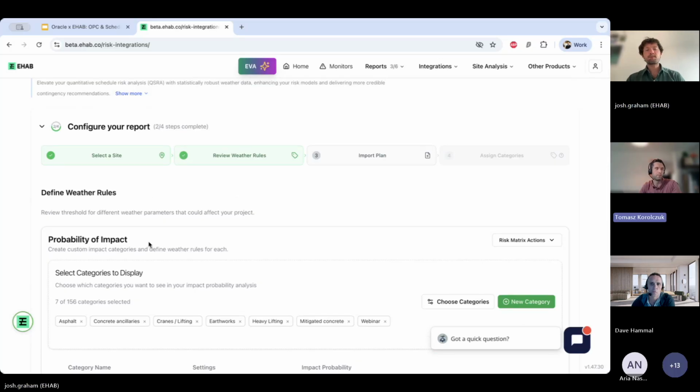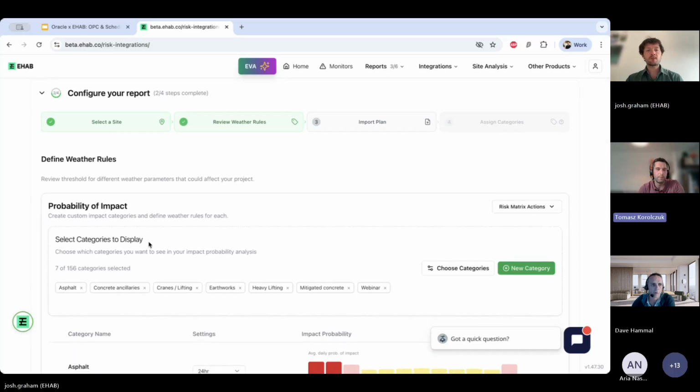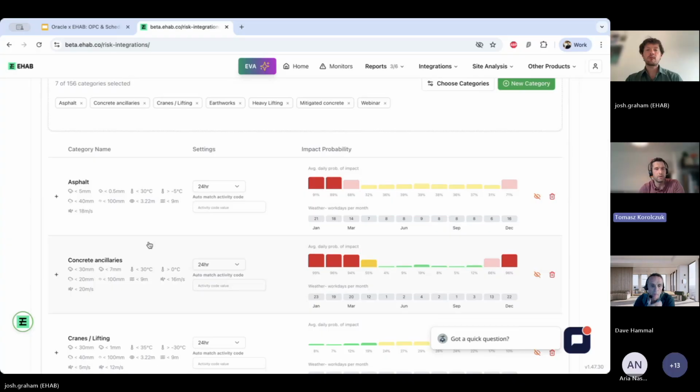That would be my question, because probably I would create different categories for concrete with anti-freeze additive, and normal concrete, right? Because you're paying for that as well. So that's additional costs. So, to fully model where you're using which type of concrete, where you should be applying those different thresholds, you can just create different categories, right?